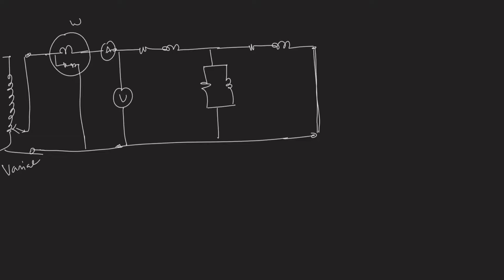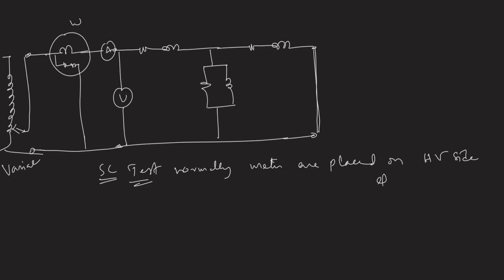Now in this SC test, short circuit test, normally the meters are placed on the HV side and LV is shorted, right?